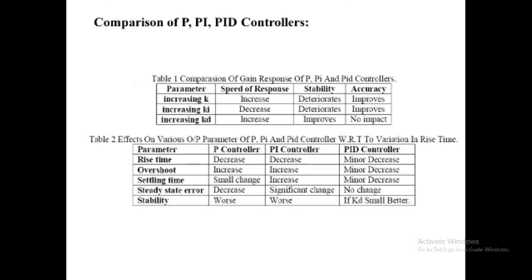So this integral control will have the effect of reducing the error, in principle, to zero value. The "in principle" must be added because there is always a limit on accuracy in any system.